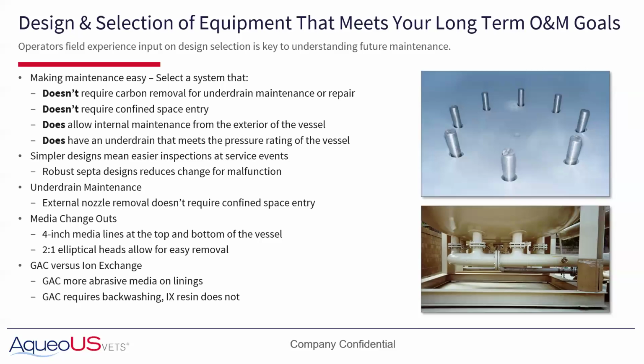Typically in the specifications, these will be designed up to 125 PSI. And that's something to think about because the vessel itself is rated to 125 PSI, but in some cases, for instance, the internal cone may not meet that 125 PSI rating. Maintenance, again, trying to reduce the amount of confined space entry for two things. Obviously, confined space entry is from a safety standpoint, and two, just having someone go in the vessel. You don't want to have to be walking around on the internal liner.